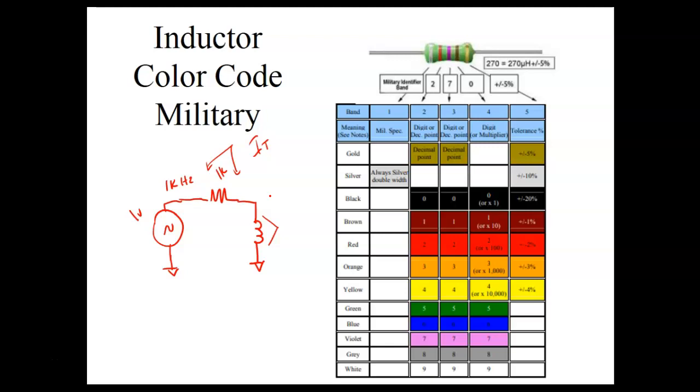If I made a mistake on this, if you look at it, it's got a 50 ohm resistor in series with it. So if I come up here and short this out, it's not going to hurt that function generator because that 50 ohm resistor will drop it. And why is it 50 ohm? Shorts hurt a lot unless you protect it. So the way our function generator works, it's got a 50 ohm resistor right here. If I short this out, that 50 ohm resistor drops it.